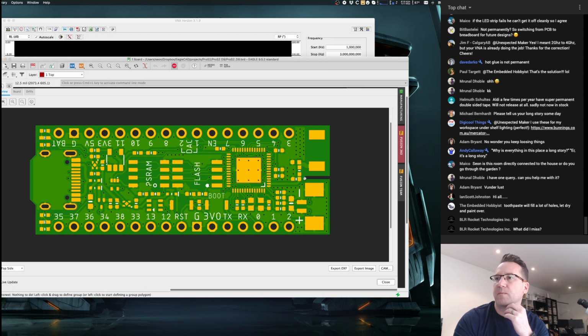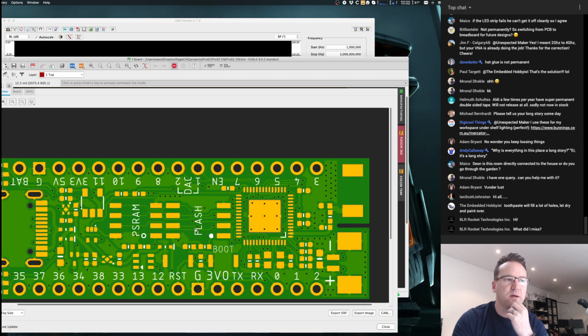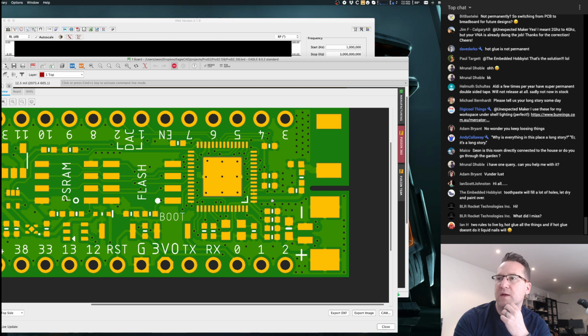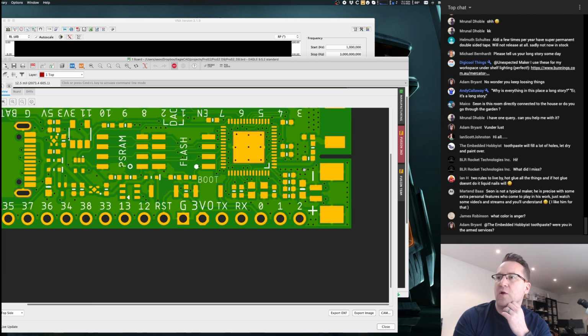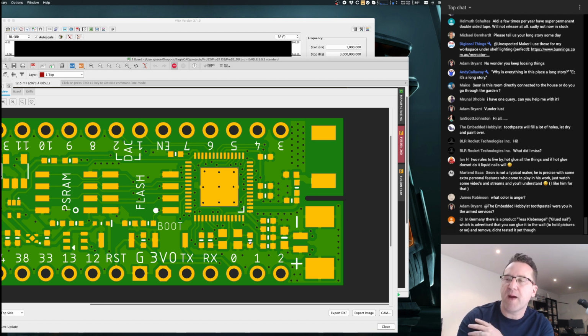So this board is very much like what we came up with on my last stream, but I made some changes still. It's going to be bigger. I made the traces through the matching network much thicker to drop the resistance between them, so it affects the impedance less. I did much better stitching around the ground plane, as much as I could. There's no ground at all under the antenna on any layer, and it's stitched much better than before. I also thickened up a lot of the power lines. So that's what I got built. That's one design. I'm going to have to go back and check what I've missed in the chat in a minute.